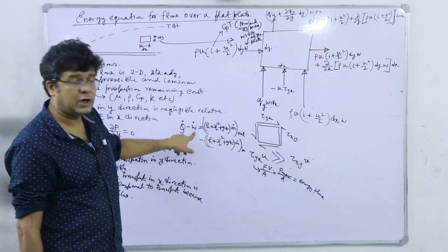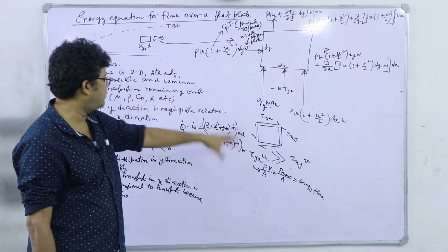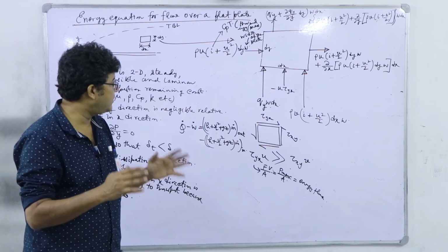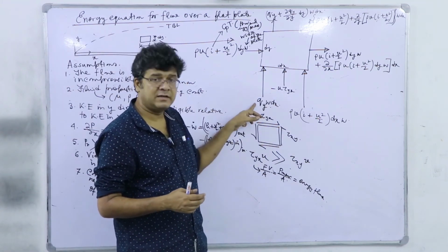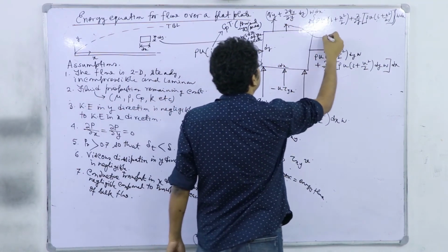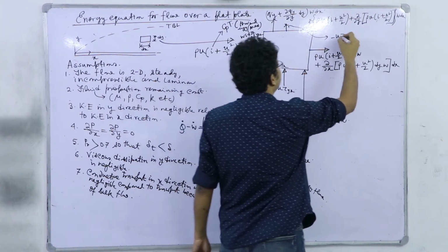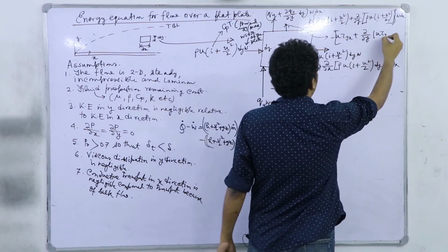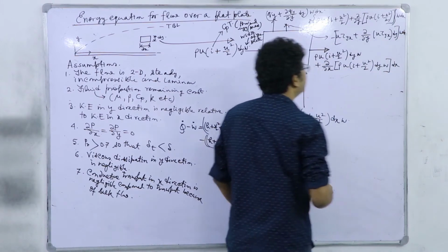However, W dot is positive if the work is being performed by the system, and that is why we have to change the sign, unlike here. So here the term will be minus of u tau yx plus del del y of u tau yx dy into w dx.